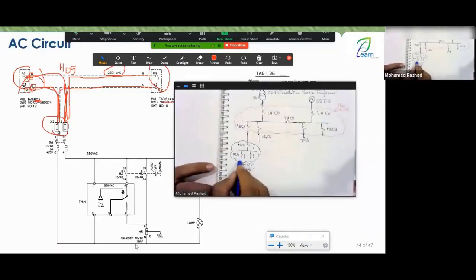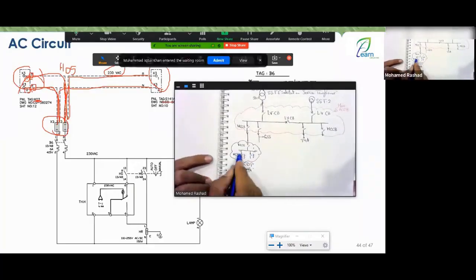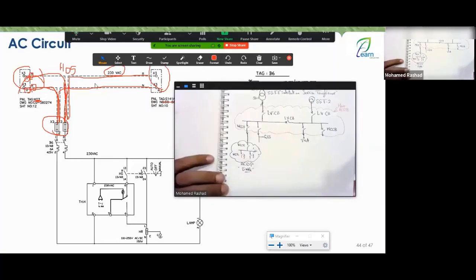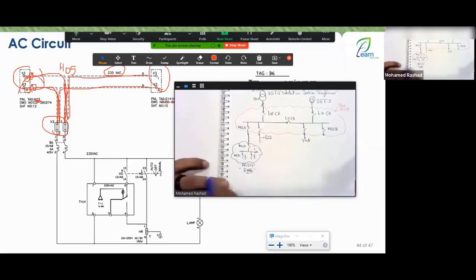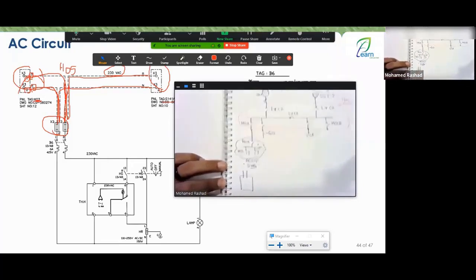Okay, so this bus bar is, of course, 3-phase. There's no debate about that. However, from these 3 phases, you only take the red and neutral wires and connect them to the miniature circuit breaker. This miniature circuit breaker is connected only to the red and neutral wires. You take these red and neutral wires, and here you have 2 fasteners.